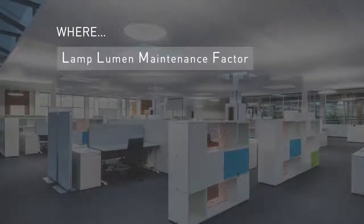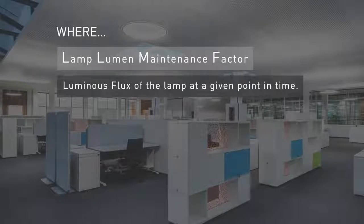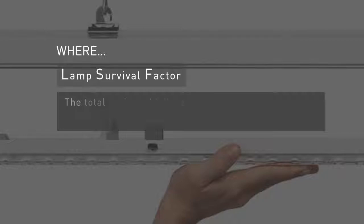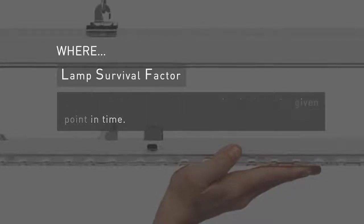Yeah. So the first one, lamp lumen maintenance factor. This is the amount of light, or flux as we often call it, that you want to remain at the end of the project at a given point in time. Next one is lamp survival factor. This is the amount of luminaires that have not failed at a given point in time.